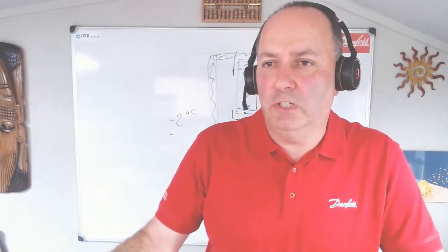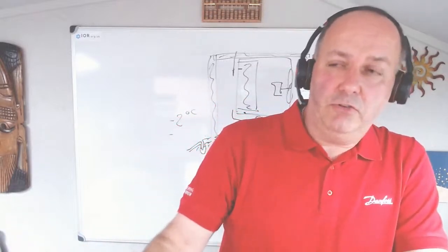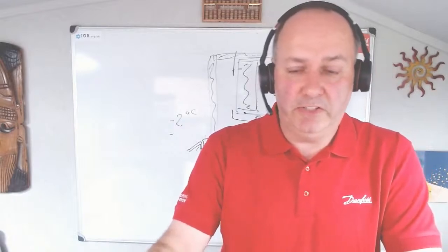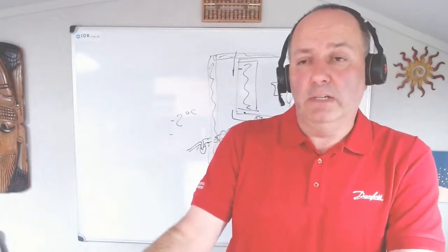Then somebody said, can we use adaptive defrosting on controllers for big cold stores? Yes, you can. The functionality of the case controllers that we make with the Danfoss Adapcool controllers, they generally drive AKV valves, and that's a sort of case controller, so it looks after the fans, the defrost, drip down, fan delay, all of that. We will have controllers with a different output for different types of valves, so that's coming.